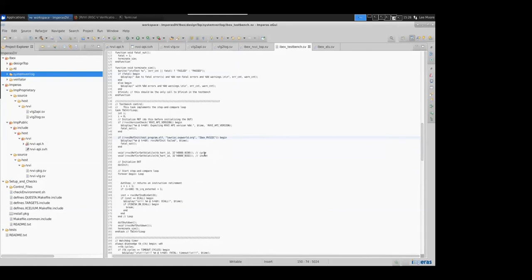A good example of that is the cycle counter. The cycle counter cannot be calculated. It's usually based upon a clock, and therefore, because we don't have a clocked representation in an architectural model, that is something we define as volatile. Now, volatile doesn't mean that it's ignored or anything, because you have to use this information.